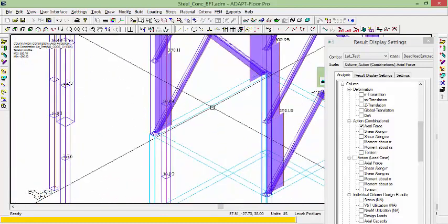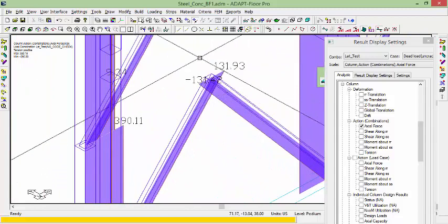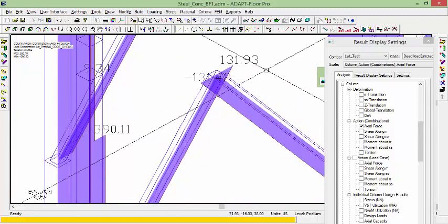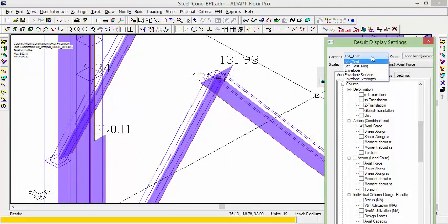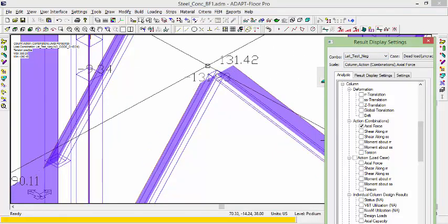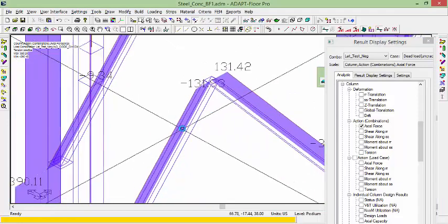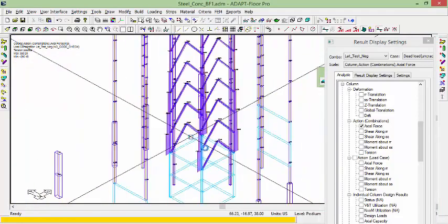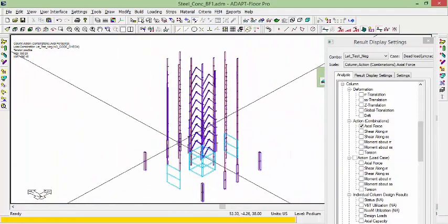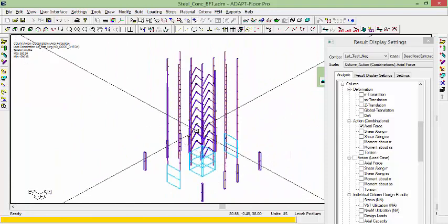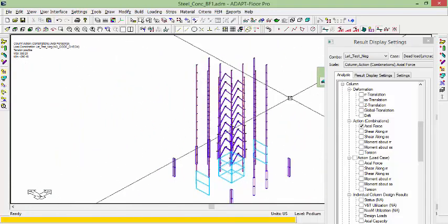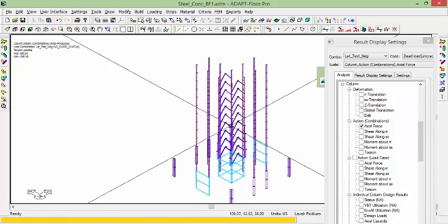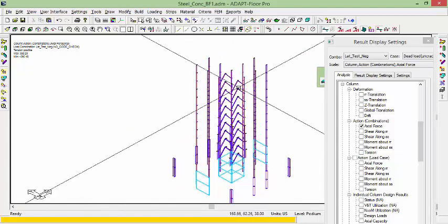And if we look at the bottom, we have one brace which is in compression, one which is in tension. If I reverse the load combo, the actions flip and it's the same magnitude. So there are ways where we can gather and equate the forces and do some quick validation. So this is how we might generate graphical results to look at actions in the different components.